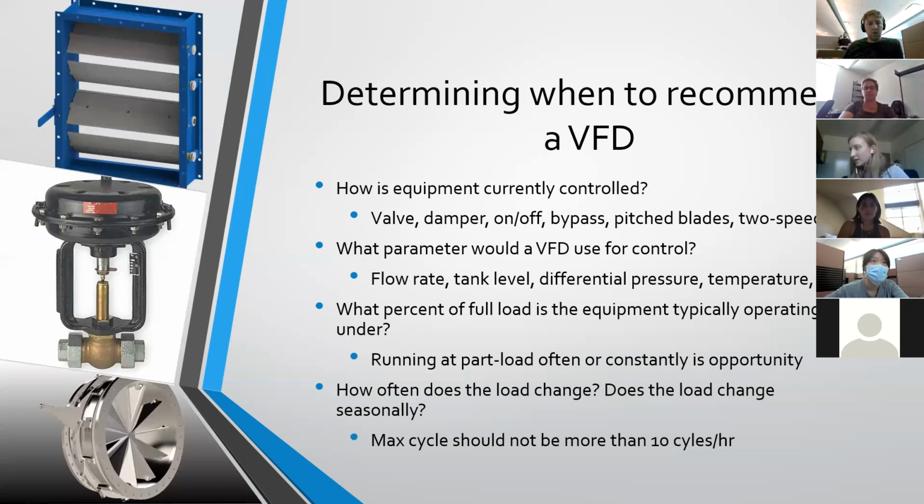Cool. So another really important thing to look at when considering whether a VFD is useful on a piece of equipment is what percent of full load that equipment typically operates at. So is that equipment designed to run at 500 GPM and that's what it's doing like 95% of the time?